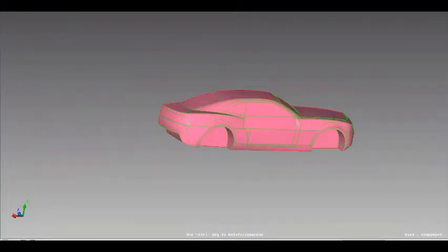One is R-tria or union jack or R-tria max. So I'm going to use R-tria max. And in the mesh process, you have different methods like flow mesher or map mesh or auto mesh. So generally for meshing an external surface for the CFD analysis, we need a better mesh flow. So for that I'm going to use a flow mesher.